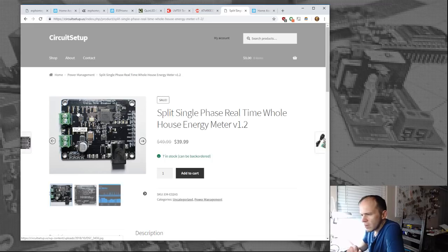You looked at the 30 amp non-invasive. So Jim, what are you going to use on the other side of that split core? Is that the split core that probably already has the built-in burden resistor, and it's probably 0 to 1 volts? I actually had tried doing that with that I2C ADS1115. I just didn't like the stability and the accuracy of it. And when I found this guy was actually showing it off on Reddit, I just fell in love with how accurate that board was.